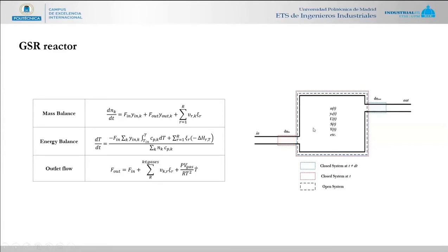There is within the reactor volume an oxygen carrier that carries out the reforming of the natural gas, which is later oxidized with an airstream, and then with a fuel stream it is transformed back to the metal to behave as a catalyst in the subsequent step.